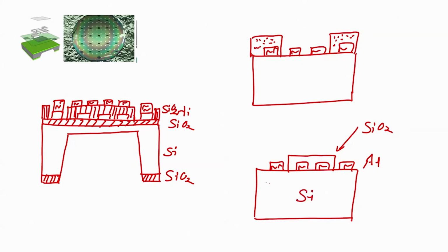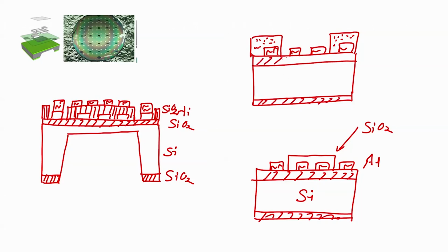I have my silicon or oxidized silicon wafer, let us say, and my conventional way of performing photolithography, like the one we discussed just now, will affect my aluminum, because silicon etchant affects aluminum.